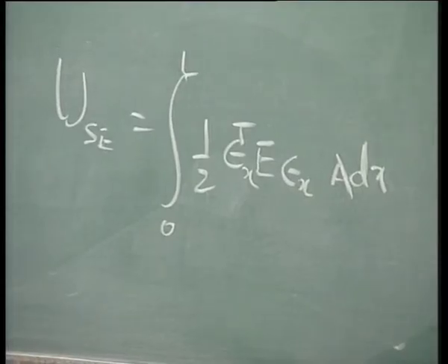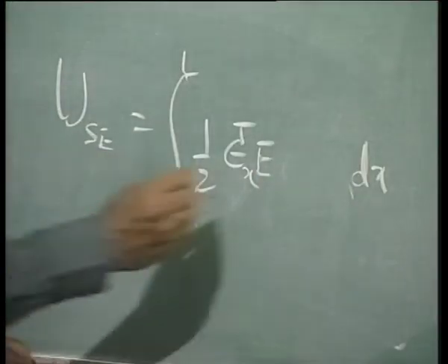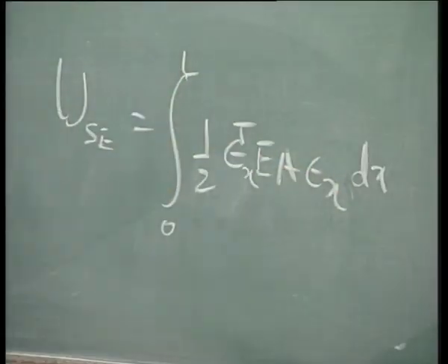Any doubts? Any questions? So now, what is the D matrix in this case, or D matrix within quotes? What is D matrix? AE, because dV we had written. So AE will be the D matrix. So this can be written as AE epsilon x. That's why I want you to develop it so that it will be very clear. You won't just copy down. Okay, that is U.